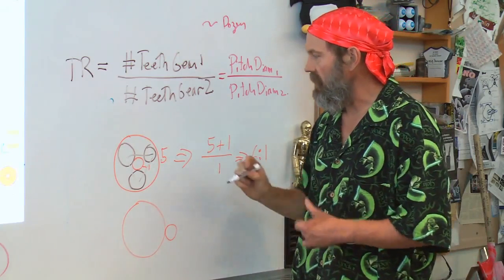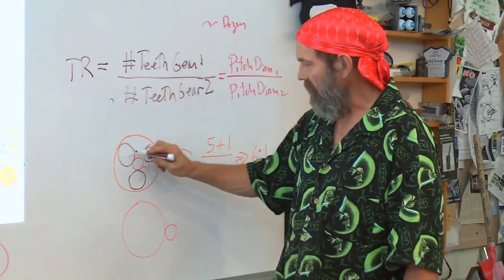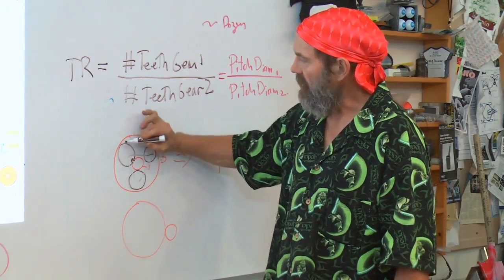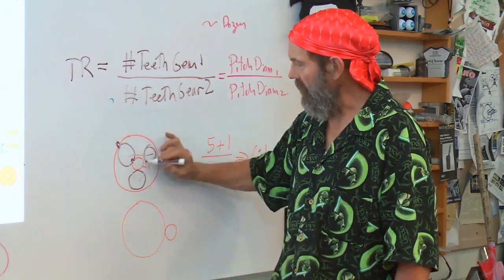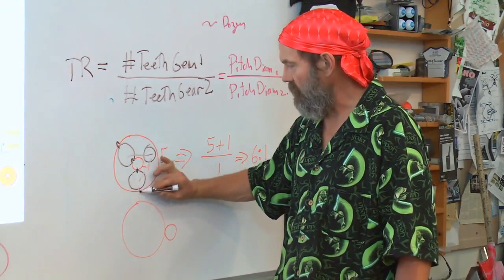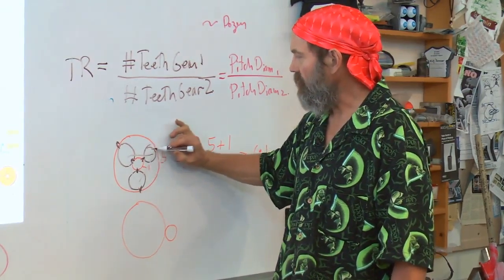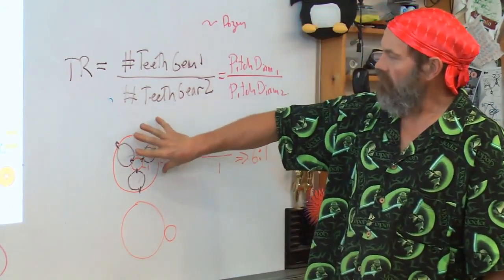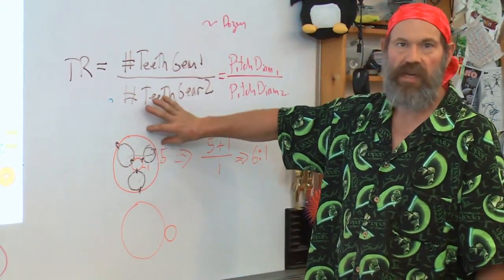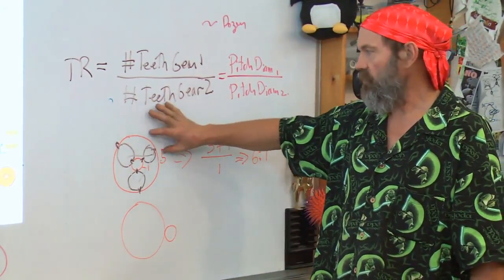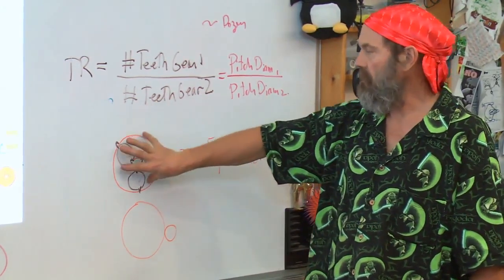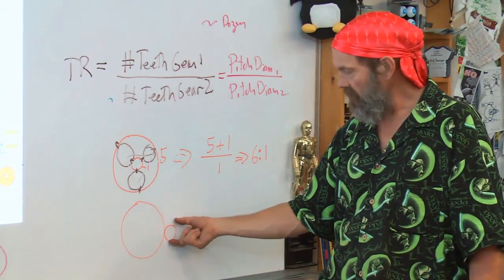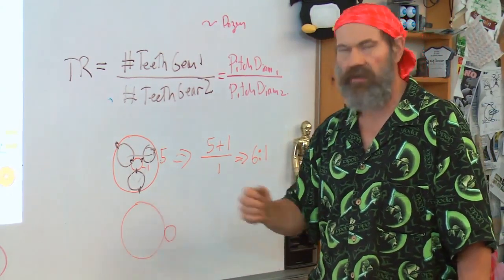But the more important thing is, with 3 planets, this tooth is engaging this planet, and this planet is engaging this ring, and at the same time I can have this tooth engaging this one and this one here. I can have 3 teeth on my sun engaging 3 teeth on the ring, so I can transmit 3 times the torque in the same package that I could if I just had a small gear driving a big gear.